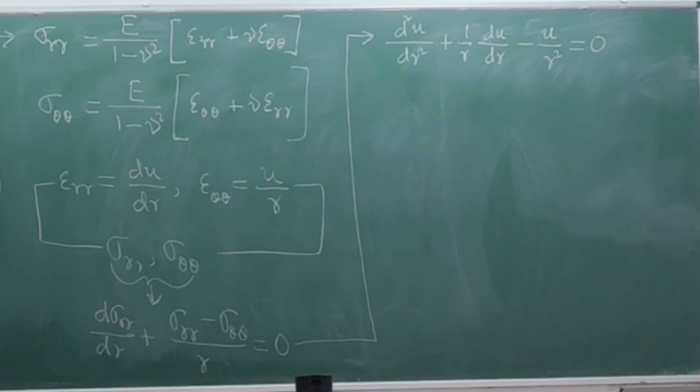And then when you come to the expressions of the stresses, nothing will go right if you pick the wrong case. So if you pick plane strain for the plane stress case, everything will come out wrong. You will think that Young's modulus is there and Poisson's ratio is there. So it looks almost the same. So why is that not giving me marks? But it's completely different. Okay.